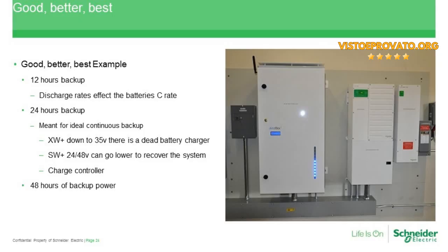A lot of it has to do with managing who's charging and when, and that can create some issues within the system. We can overdrive batteries and cause something we call thermal runaway, which is unfortunately this photo that we see here on the right. So it is something that we want to strongly press you towards, with that idea that doing an AC and DC coupled system together is not a great idea, and we don't recommend it.